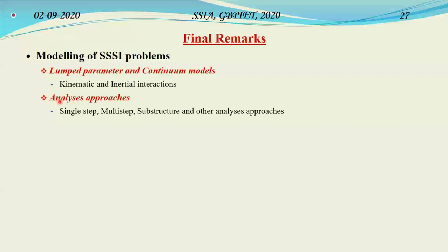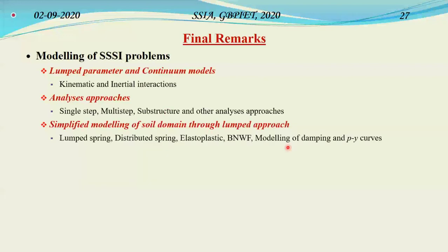We looked into a few overviews of the analysis approaches: the single step, multi-step, substructure and other analysis approaches. We talked about the simplified modeling of the soil domain through the lumped approach, where we showed lumped spring, distributed spring, elastoplastic model, BNWF, importantly for the pile soil interaction modeling,